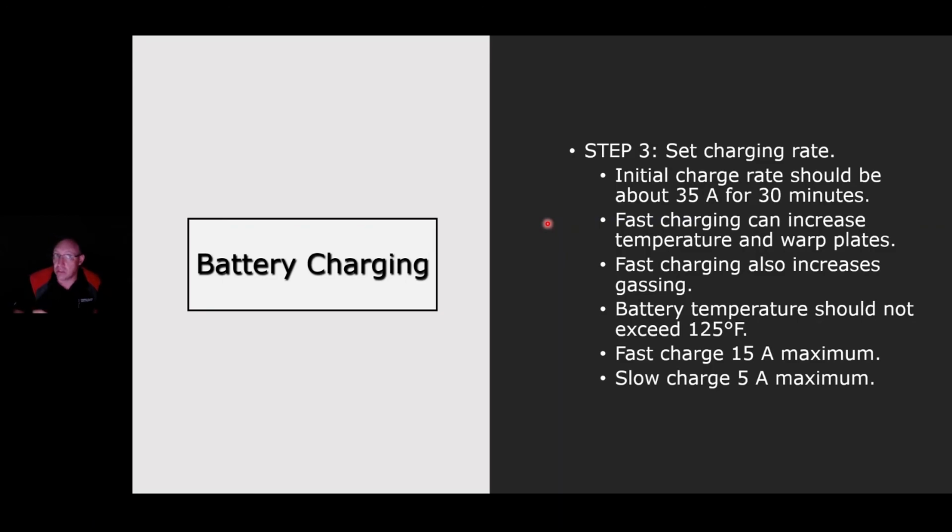That's really, really hard on the batteries, and you're taking a chance of burning down that battery. And when I say burning down the battery, I mean causing the battery to fail, okay? So just be careful. Keep the amperage rate as low as possible when charging a battery. Takes longer, yes, takes a lot longer, but a lot better on the battery, okay?